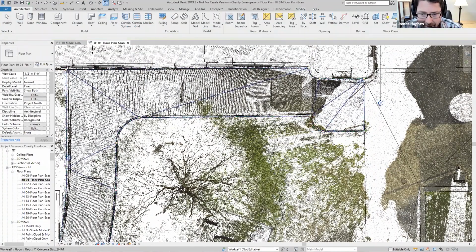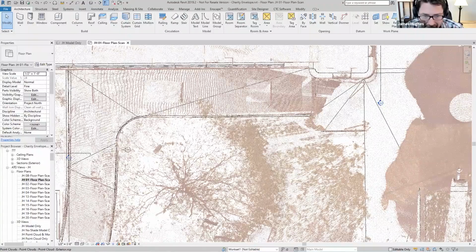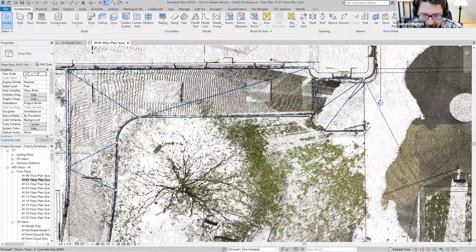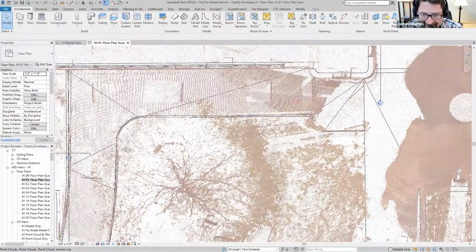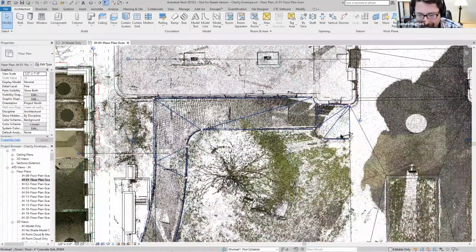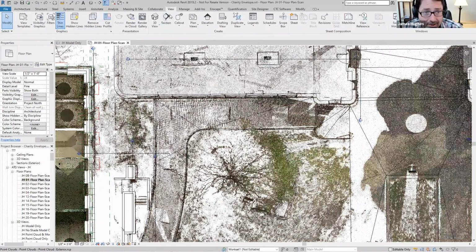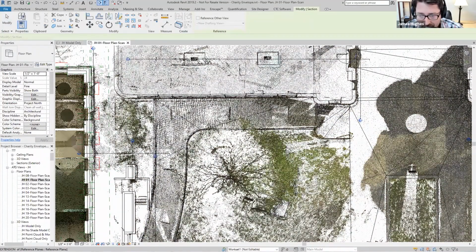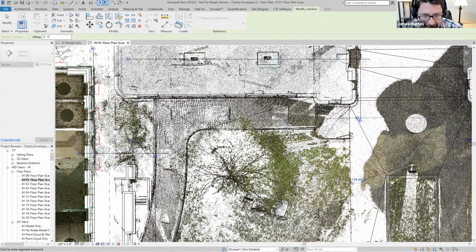And that's not very helpful to do in plan, so the way I did it was I cut a thin section through here, looking at just about a 2-foot strip of it, and it allowed me to, in section, grab a point and maneuver it with a nudge command, just arrow up and down, and get these to exactly the height that they needed to be. So if I just cut a section through this real quick, we should see this thing elevated as it should.